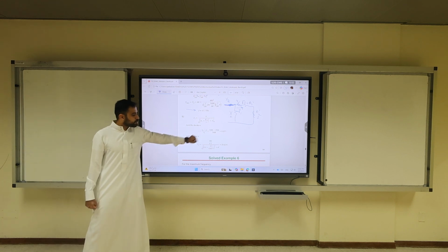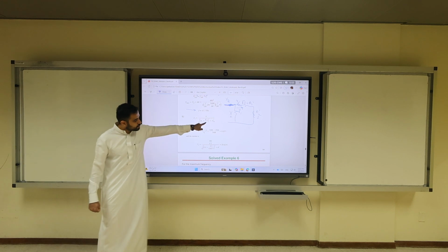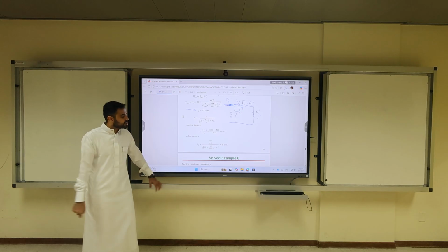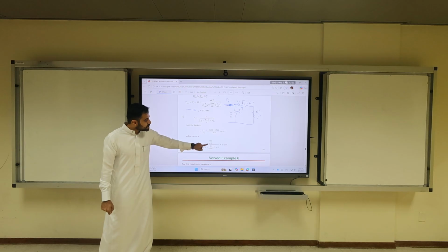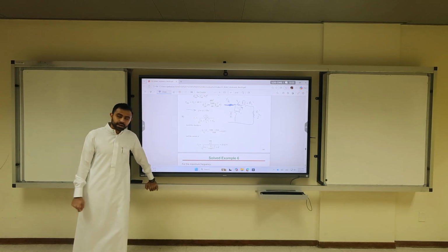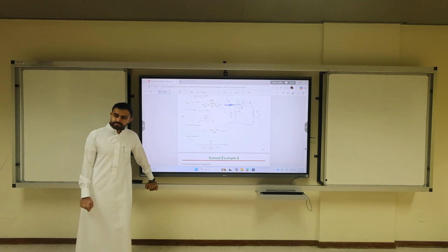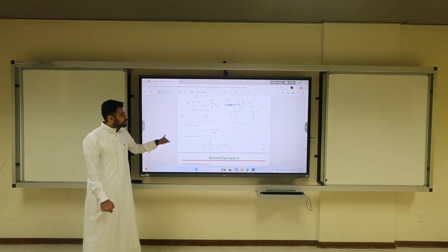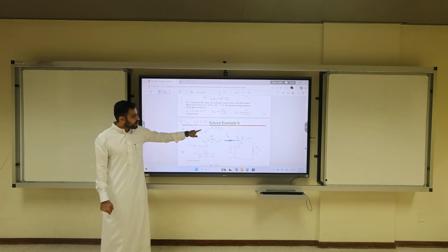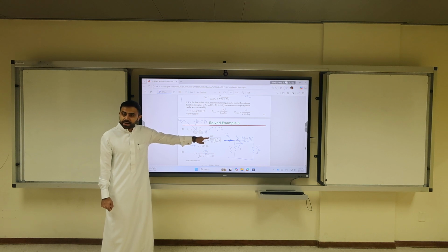So what is the slip we already calculated? You have to plug the slip here. Don't forget the slip. It means you also have to calculate the slip at 67 Hertz. So this is 360, 480 over square root of 3. Here, is he using phase or line to line? Phase. He's using phase. Here, he's using V as 480. So this is a mistake, right?